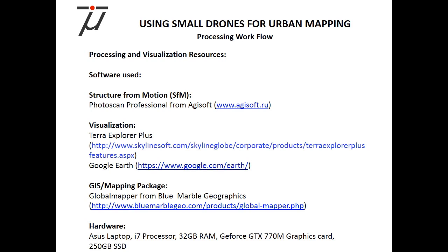We can afford to use cheap cameras. We don't rely on geometric stability of the platform itself. In fact, we embrace some of the fantastic firmware geometry-changing functionalities embedded in these, like autofocus, for example, because one of the byproducts of structure from motion algorithms is a calibration for each exposure of the camera. So it doesn't matter if there's varying camera geometry from one picture to the next. The next point is that you can actually mix cameras in one project. You can use a GoPro for this and another camera for that. Put it all in one pot and it will adjust.